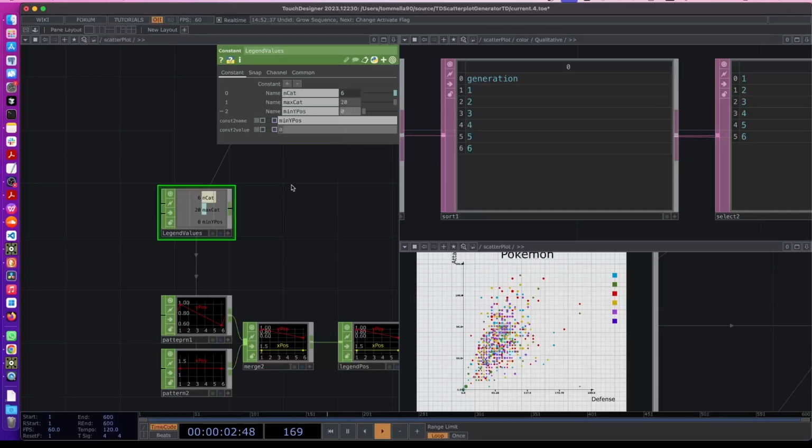So let's say that we now have 6 categories and 20 max. Each category should occupy, if we had 20, 1 divided by 20. And 20 can be referred to like this. We can take this const 1 value and drag it here as a reference. So we can do 1 divided by const 1 value in parentheses. And this is in the case we have maximum categories. And then we multiply this by the actual number of categories we have, which is 6.